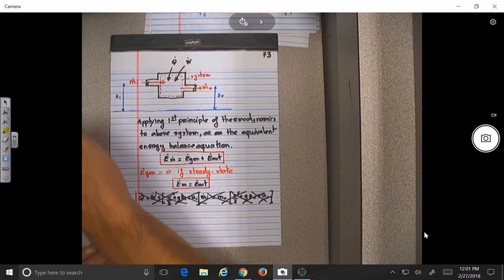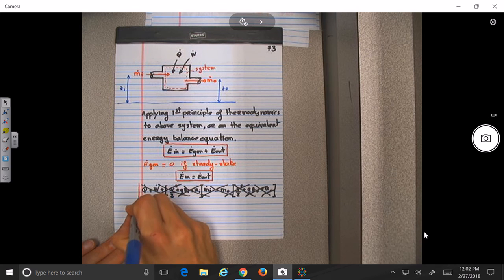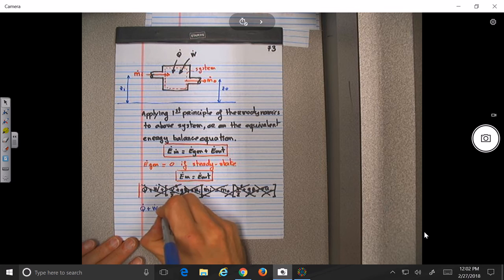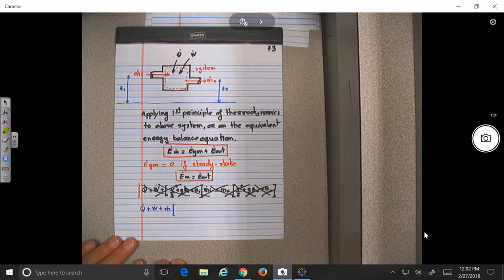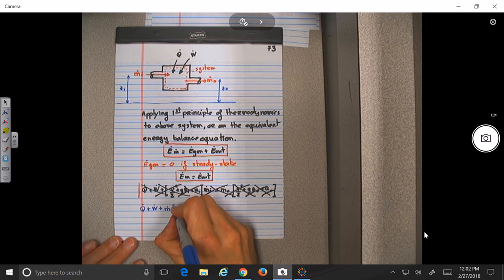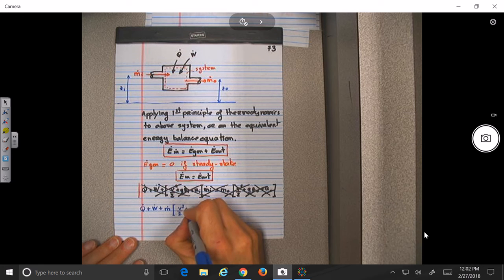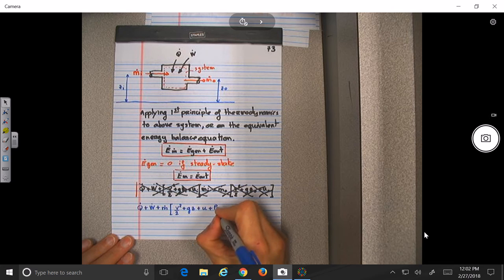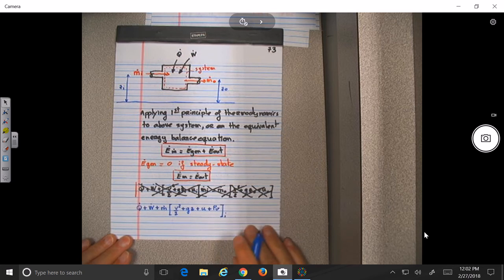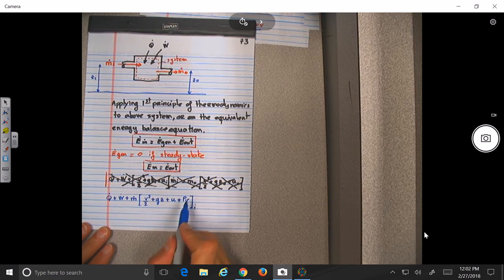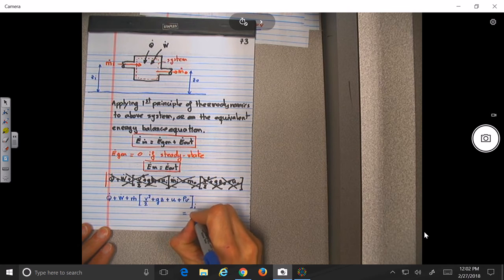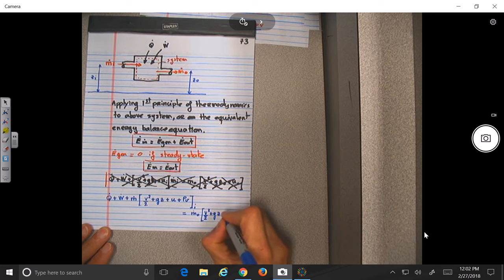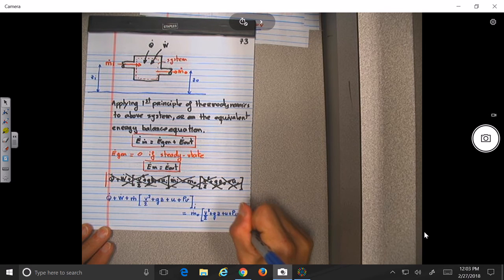Maybe let me do it in blue. So what is the energy going in? We're going to have Q dot plus the work plus the m dot, not going to change anything here, so I'm going to do the v squared over 2 plus gz plus u plus PV input. Okay, and I will explain it now. I forgot that term over here. And this should be equal to what? To m out of v squared over 2 plus gz plus u plus PV out.